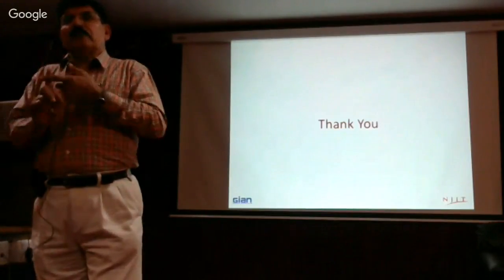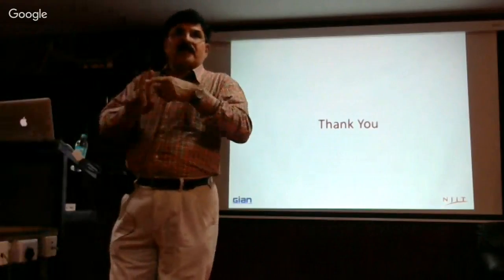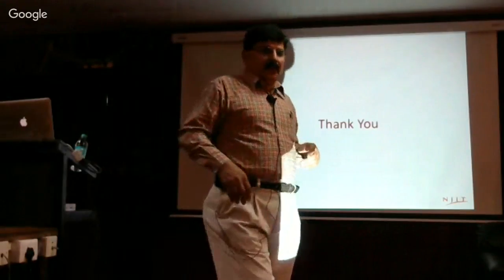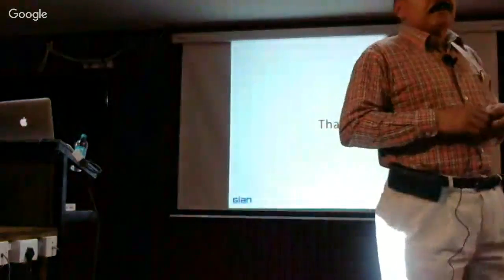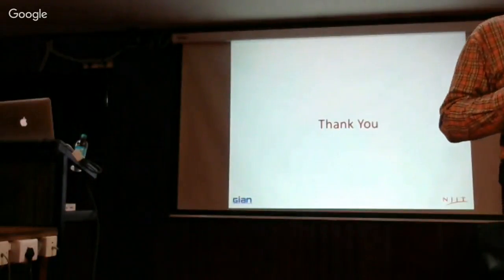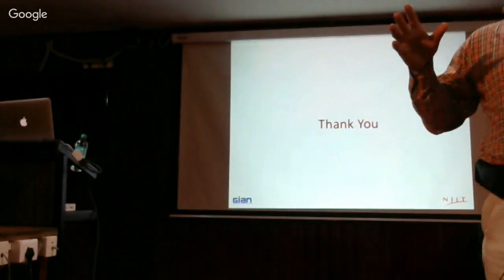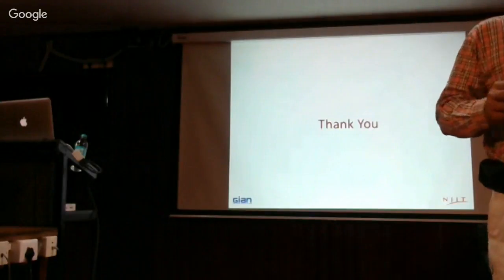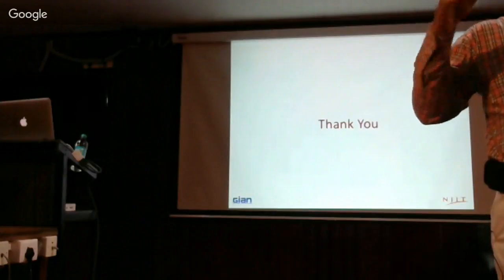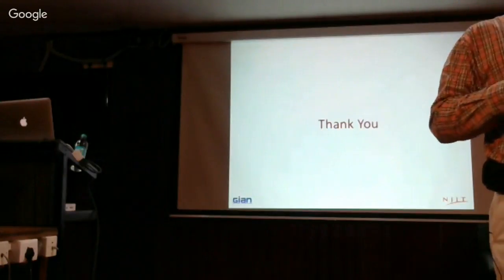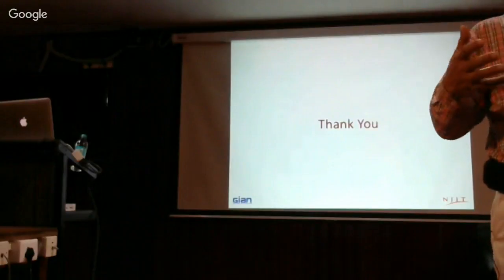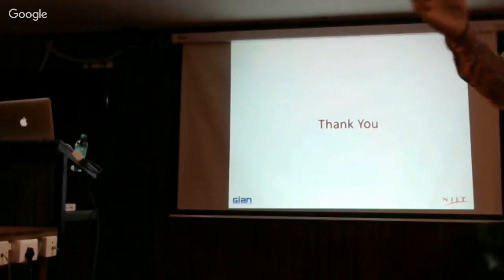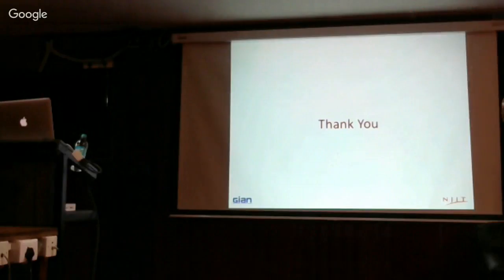What is the difference between the Cadence Spectre analog simulator and HSPICE? Have you heard about HSPICE? The Synopsys tool has HSPICE. What is the difference? With HSPICE, you can get state-of-the-art models, even for 7 nanometer transistors, with experimental results. What they do is go to, say, 65 nanometer or 45 nanometer technology, make the devices, and extract the parameters from a test set of devices. Then they make circuits and compare them. Then they release those values for simulators.